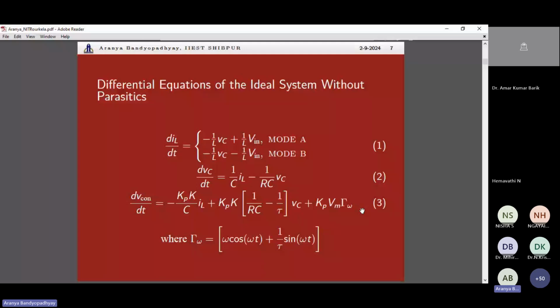One thing that I have done in my work at least is that, at the very outset, I was talking about the problem of analyzing stability of an inverter. Why? Because there are two frequencies in it, and all the theories are developed for analyzing stability at one frequency only. That is why it is very simple to analyze stability of a DC to DC converter, but it is not so when you come to a converter with two or even three frequencies, which is the case of an AC to AC type of converter.